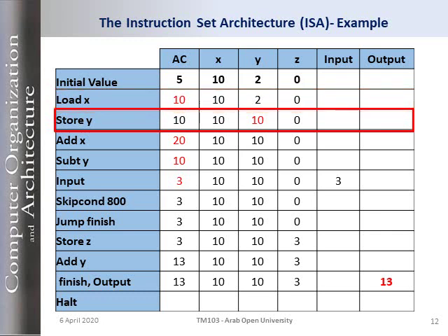Okay, let's move on to the next instruction. Store Y. What does it do? Store Y means whatever is in the accumulator, we have to store it in memory location Y. So what is in the accumulator? We have the value 10. So we'll store 10 in Y. So Y will change from 2 to 10, as you can see.